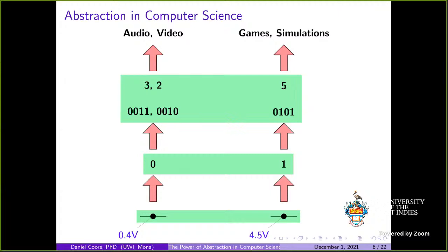The most common representation of computation today is using electric signals, namely voltage, and of course current is another state variable in any circuit. And what we'll do is abstractly say, okay, the voltage at a point, if when we measure it, it's less than some low threshold, we'll call that a 0.